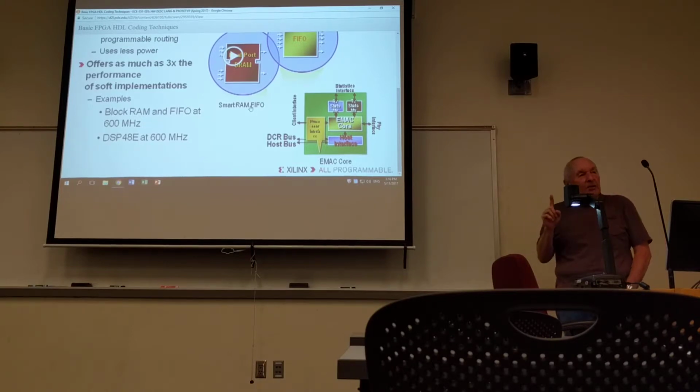What that implies is that you are going to be synthesizing over and over again until you get what you want. Because every time you change a synthesis option, you have to resynthesize the design, and then you have to redo your timing analysis and everything. But you have to try these different options to get what you ultimately want.